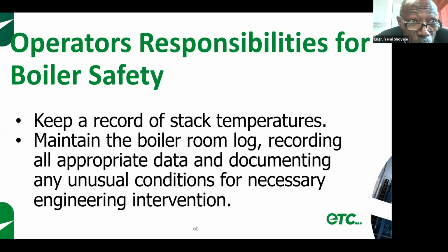But the question is, why would you have a high dissolved oxygen in your feed water? It's because either you don't have a degasser installed. I have seen some funny looking factories. Or where they are installed, it's not working very well. The one I showed in my presentation is a type that has a perforated tube inside the degasser at the bottom, through which low pressure steam is passed, and this forms a bubble continuously. And when that happens, you are able to exhaust almost all the dissolved oxygen. I don't have the right figures now, but I think about a very small ppm.